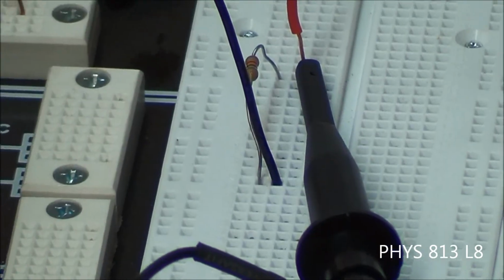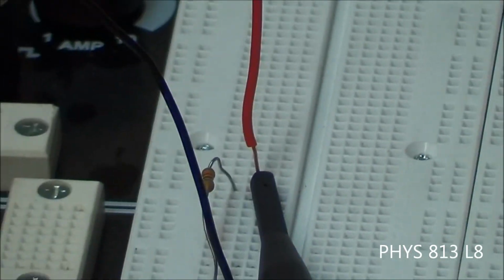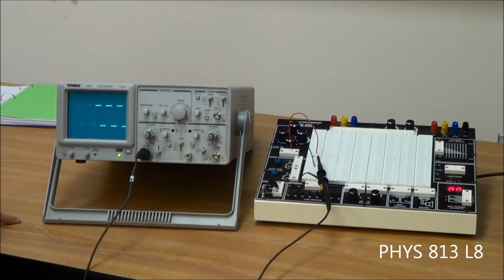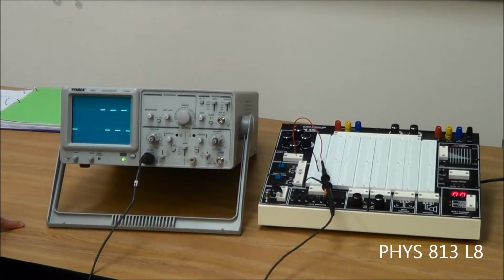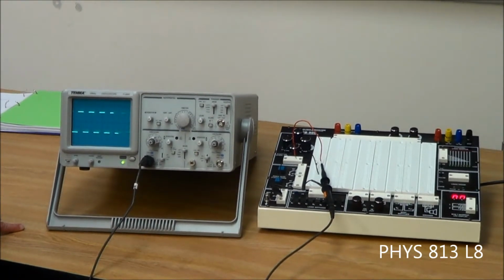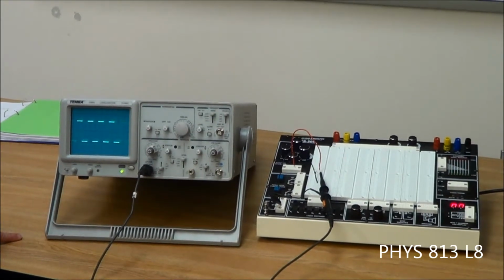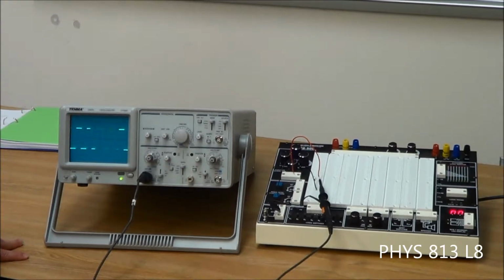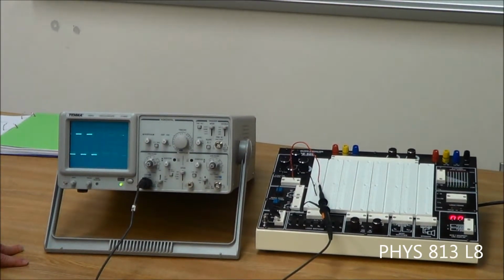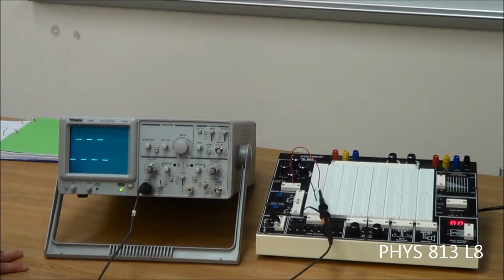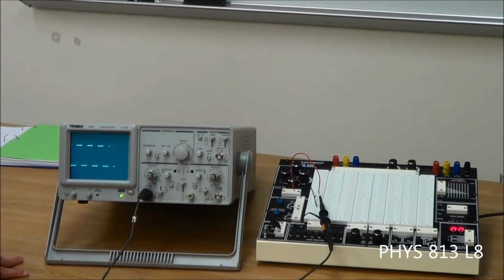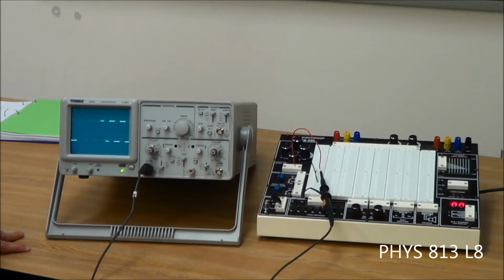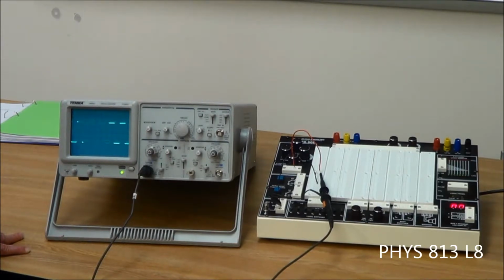Okay. Now, I can't emphasize enough that when you're connecting these things, check to make sure that things are in the row that you think they're supposed to be in. So if something doesn't work right, check that first. Also check to see that your circuit board is turned on. And the reason I say that is from experience. After spending several minutes trying to figure out why something didn't work, I realized one time that the circuit board was not on, and another time that I did not have things in the same row that were supposed to be in the same row.